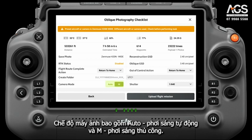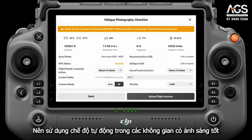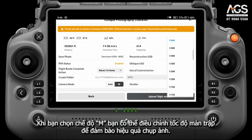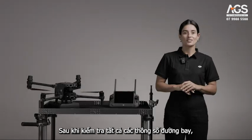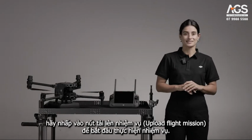Camera mode includes auto, automatic exposure, and M, manual exposure. It is recommended to use auto in well-lit scenes, and manual exposure can be used in low-light scenes. When you choose M, you can adjust the shutter speed to ensure the shooting effect. After checking all flight route parameters, click the Upload Flight Mission button to start the task.